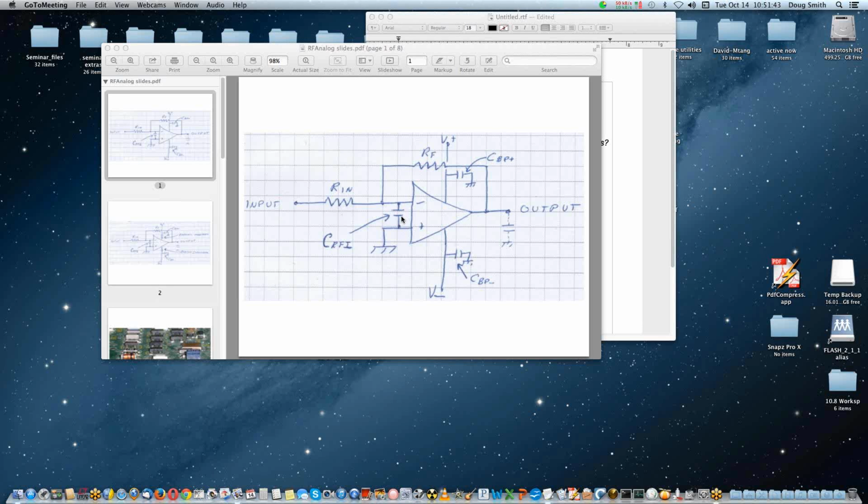Our attendee said multi-layer. Okay, then I'm not sure what a ground ring means. I mean, there are voids in the ground, which we call moats. If the intent is to isolate it, as you say, Doug, then the key is to have the impedance high enough to isolate it.